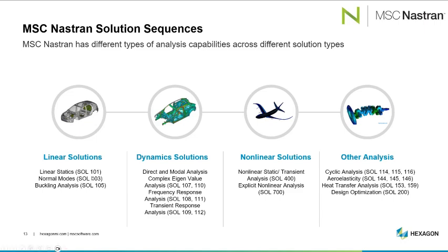If we talk about the Nastran solver, I think they usually refer to this as SOL 101. This is simply an internal reference with an ID that says this is linear statics. Do you need to know these? Not really. There's only two that we typically know really well. 101, which is linear statics, and probably SOL 400, which is the more advanced nonlinear solution sequence. So we'll talk about SOL 400 towards the end of this as well. So don't worry too much if you see a number or a SOL. It's simply a different way of saying it's a certain type of analysis.